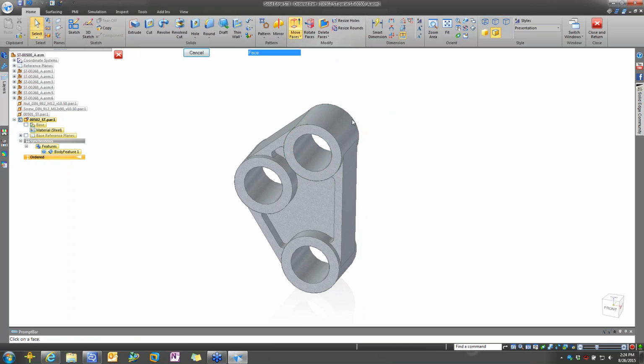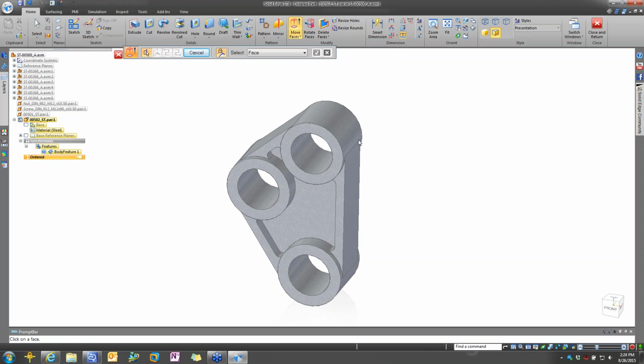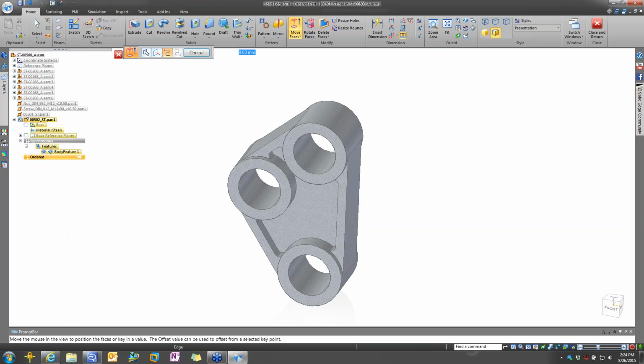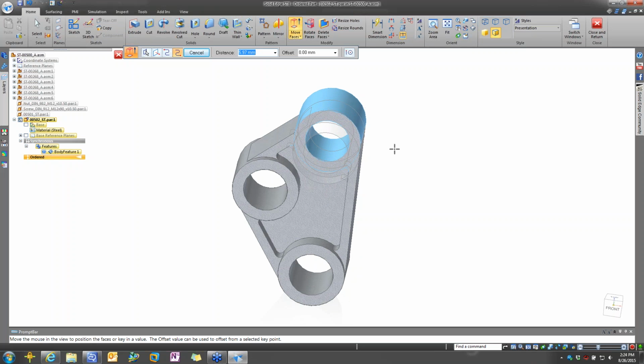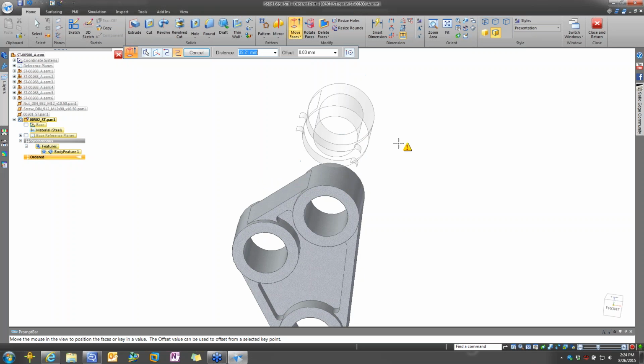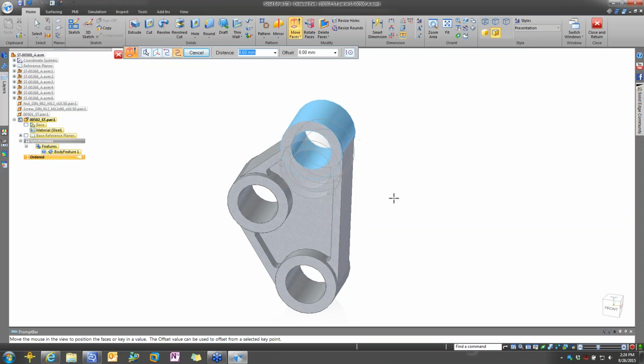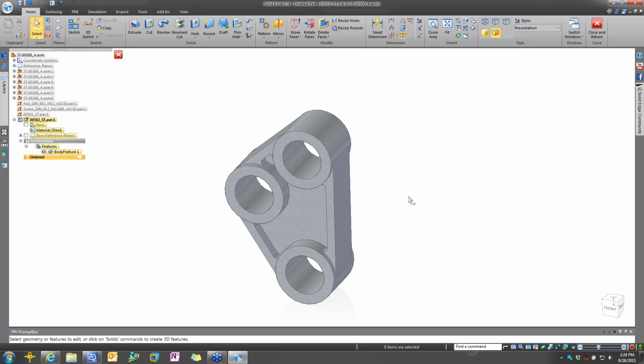And we'll do that again with that simplified move face tool. And I may say, let's move that face and that face. Again, we want to move it in a specific direction. And you'll notice again, it's not doing exactly what I want it to do. It's kind of moving the boss, but again, it's not moving the faces tangent to that boss. And as we get to a certain point, we may run into some errors. And again, this is what you'll see in a traditional CAD tool.